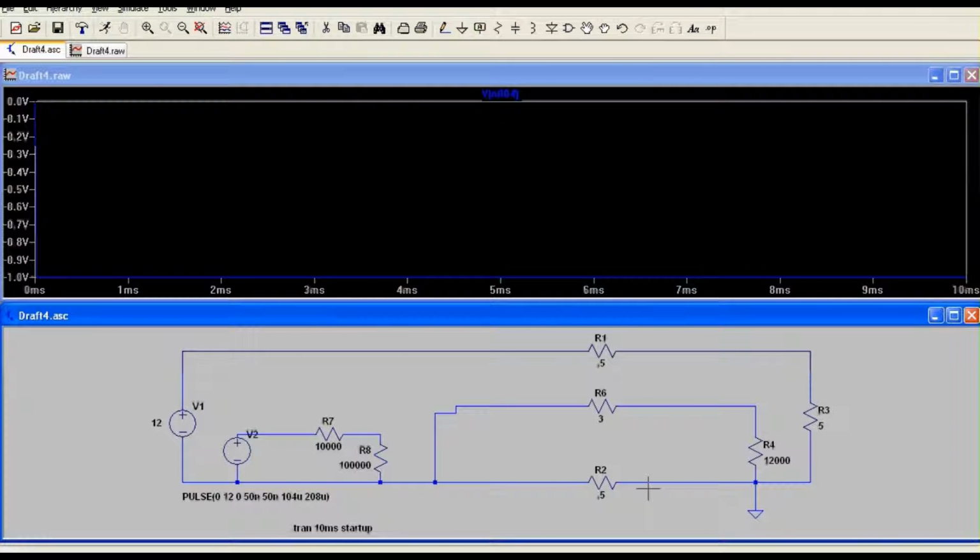So we know that there's a volt being dropped across here, and normally in simple circuit analysis, you'd put your common probe at the supply 0 volts, and then measure about the place to see all the voltage drops. So thinking that way, you can start to see, well, if I put my common probe this way and measure back the other way, you'll be measuring those voltage drops in the negative. So that's what we're seeing there.